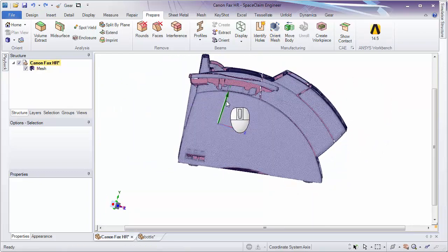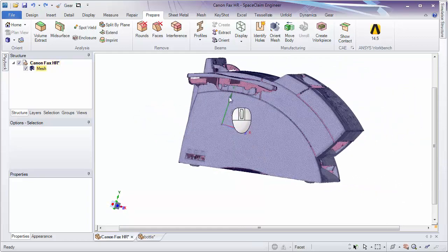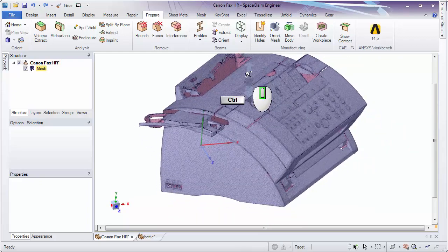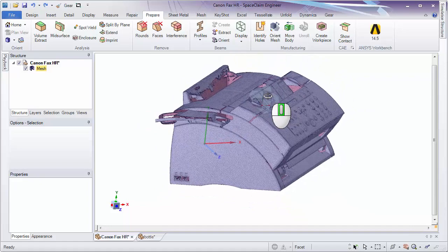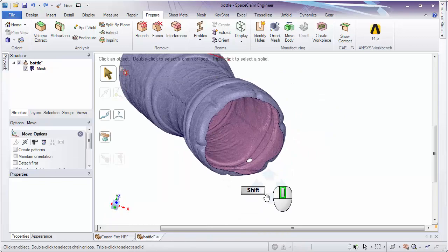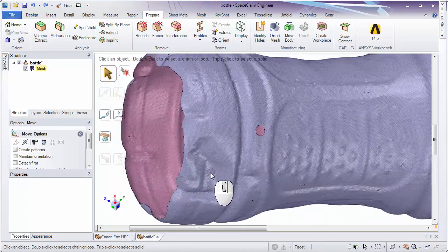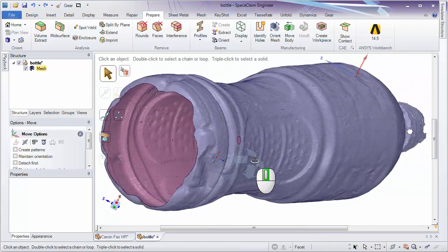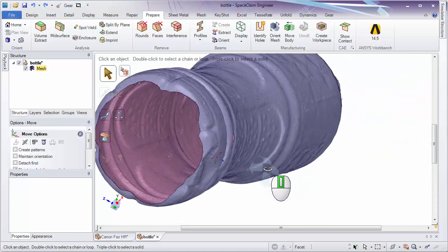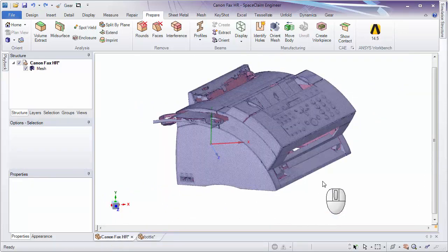So here we can see our world origin, XYZ, and it doesn't really look like it's aligned to anything in the part. It's at an angle in one direction and an angle in another direction. Now we're going to look at a boxy prismatic part like this, and also something cylindrical. But as we see from many scans, a lot of times we have organic geometry, so trying to fit a cylinder through the center of all the data may not turn out to be the best or the right workflow. So we'll explore a couple of different methods in orienting these to the best center line.